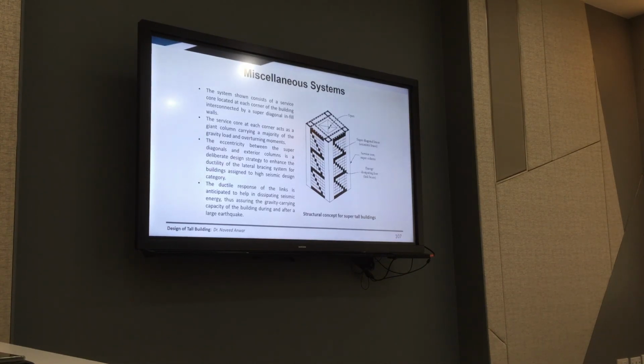Excellent. Next one. About that, in order to achieve ductility design, we need to design a structure in which the flexure yields first before the structure reaches its shear capacity. Excellent. Very good point. Yes. Yes, that's true. Okay, good.